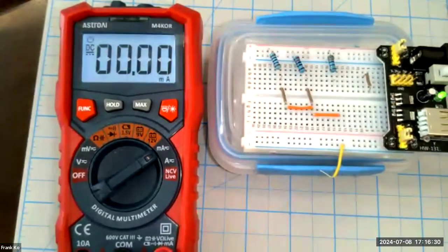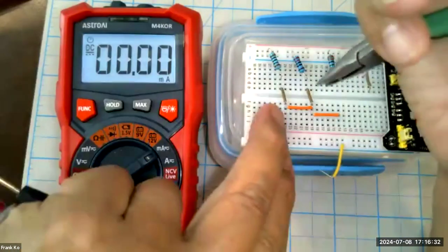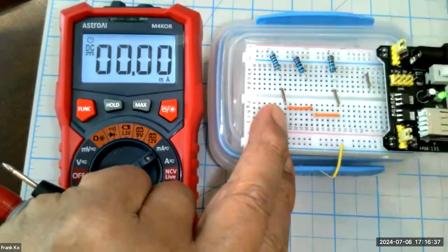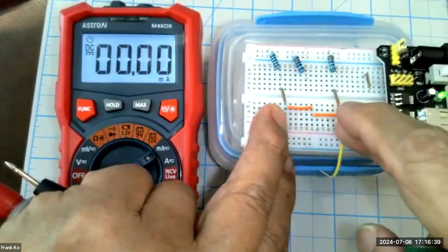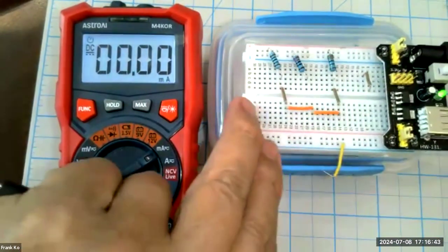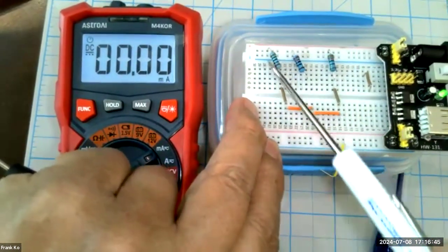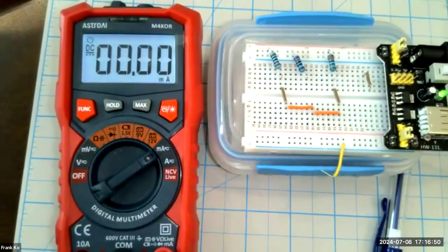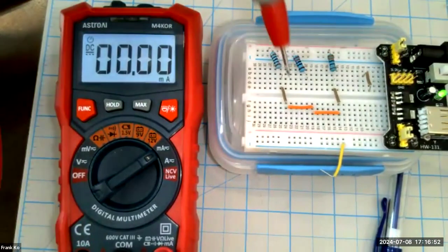All right, the next fault condition was saying something happened to the second branch, so I very easily moved this from here to here, meaning I have to reconnect the third branch to be parallel with the first branch. So the third branch, R3, is in parallel with the first branch, giving me an open to measure for current. And we predicted 65.16 milliamps.